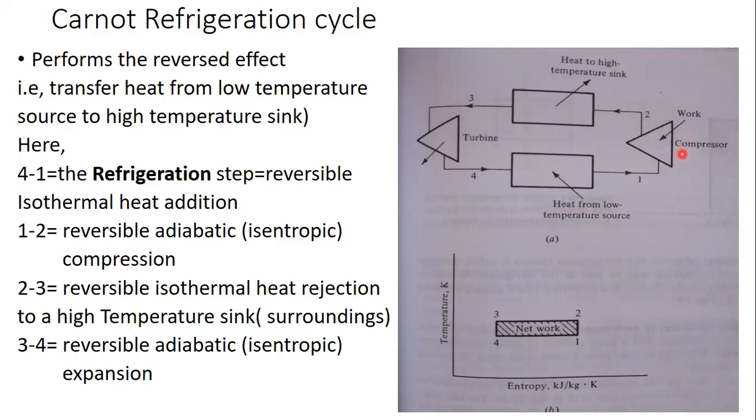When you get a chance, please have a look at all the components of our household refrigerator. There you can see a particular portion producing a humming sound. That is the compressor, and that compressor is doing this work. It will be energizing this working fluid, which has already taken the heat from our freezer compartment. In order to make that working fluid reach a level where it can reject the heat to a high temperature sink, that is our surroundings, it needs more energy. And that extra energy is supplied by doing work by means of this compressor.